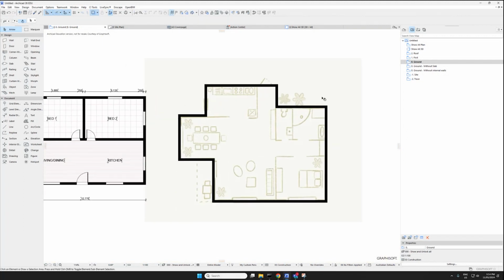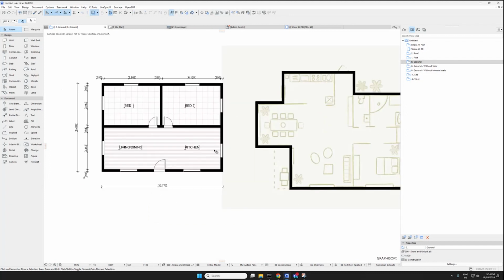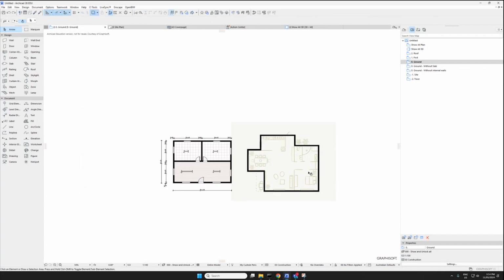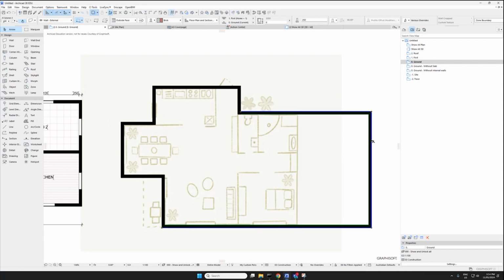Okay, so that's one way you can trace things very quickly, and resize objects or drawings, or even your whole drawing here. If you wanted to resize it, you can go Control K, OK, change that. All right, and if you want to change a structural wall, you can select the adjacent walls to it, and then click on the blue line, and either offset all edges or just offset that edge, so you can stretch that.